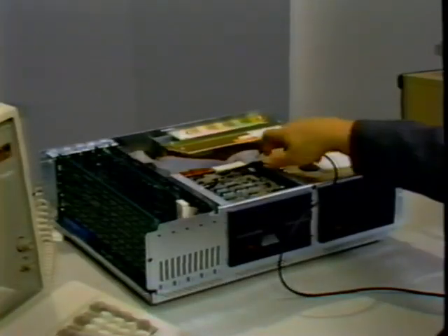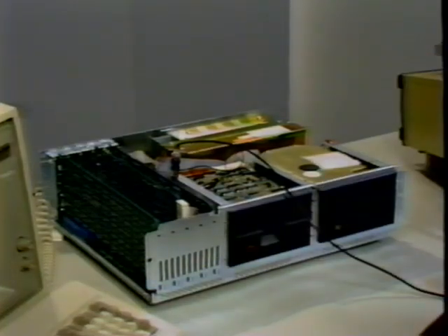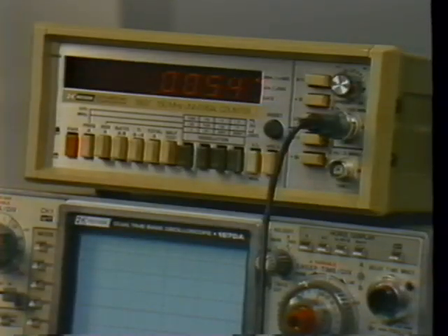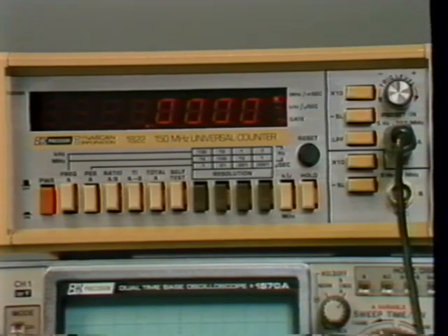Now that we know how to operate a frequency counter properly, let's look at some common operational mistakes. A very common error is to attempt to read the frequency of a square pulse directly. Most inexpensive counters are not designed to do this. As you can see, the results are somewhat inaccurate. Another common mistake is to set both the probe and the counter to the ×10 mode.